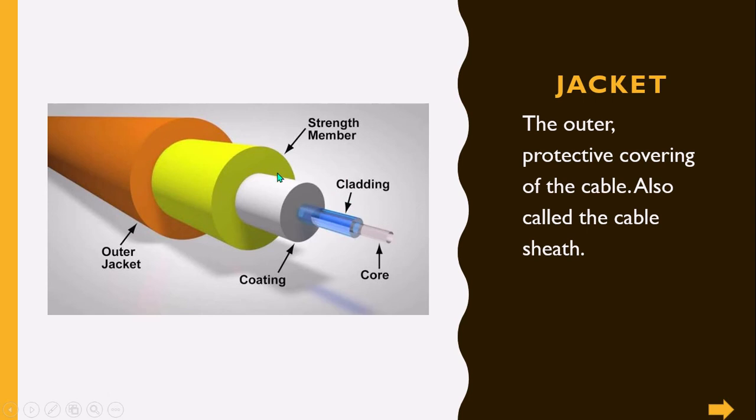As the bare fiber is easily broken, a fiber optic cable jacket is needed, so it is very important in cable. It provides protection for the shielding and conductors within the cable. The cable jacket is the first line of moisture, mechanical, flame, and chemical defense for a fiber cable.